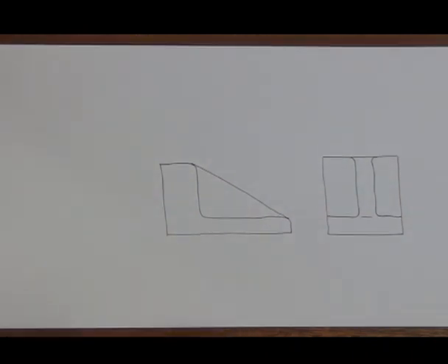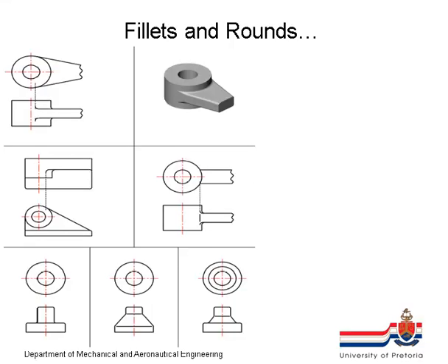The person making the drawing cannot change how the part will physically look. So the same applies for other shapes. Again, rounding and tangency. There's a big rounding with something tangent, so we won't show a line.